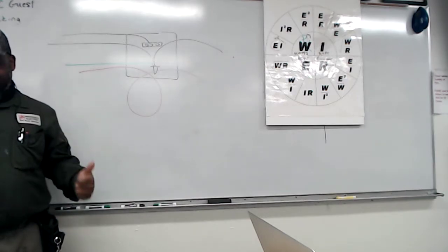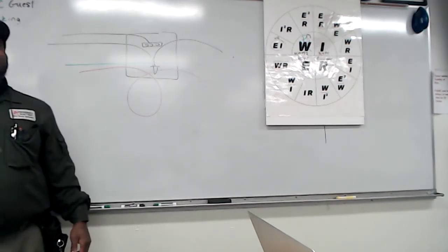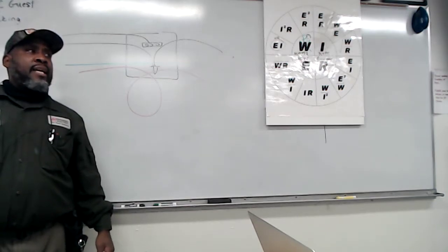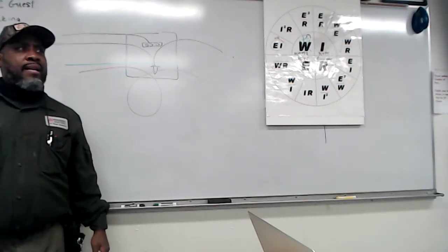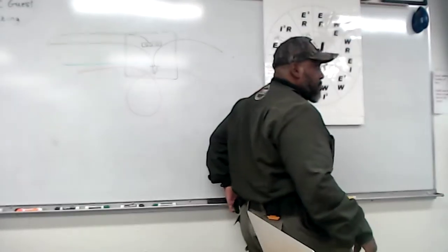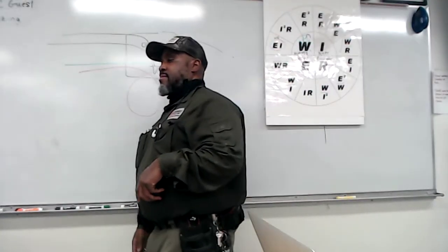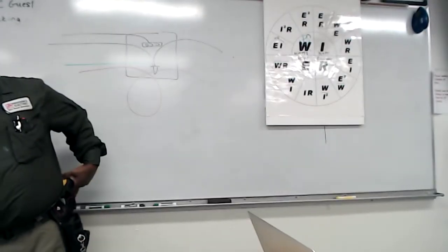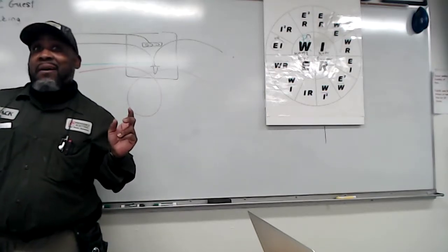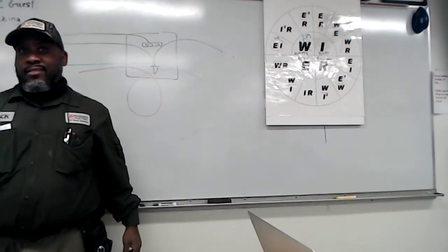Clamp fill, same thing. If I have an internal clamp, not an external clamp, then it gets counted one time no matter how many I have. Here's an internal clamp. There's one here and one there. The clamps are internal, in other words, clamps inside the box. We use them all the time. But if you do see one on the exam, it gets counted one time. Got it?